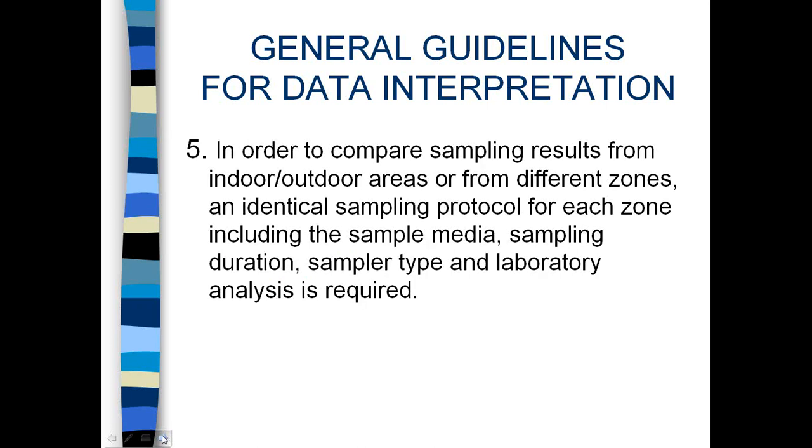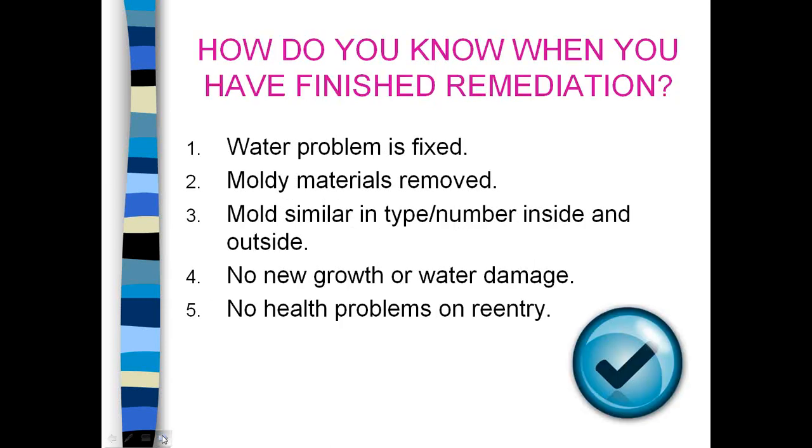In order to compare the results from different zones, use an identical sampling protocol. And finally, how do you know when you've finished remediation? Primarily, fix the water problem. You then address your mold issues. And finally, no health problems on re-entry.